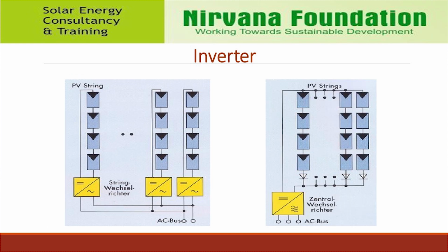Central inverters. Central inverters centralize the plant's power into one place. String combiners connect wires from each row of panels together, then recombiners combine the output of the string combiners together to feed into the central inverter. Central inverter units are physically much larger than string inverters, use longer wires and can convert more power per unit. Contrast that with a string inverter, where much less power is lost if one goes down.